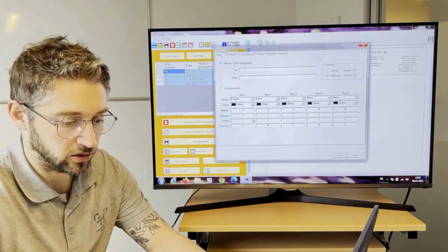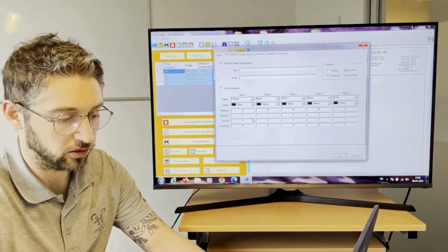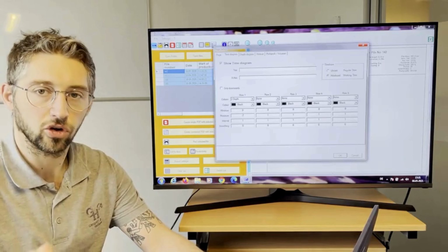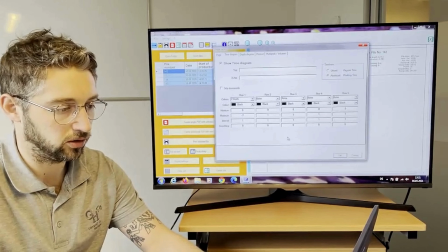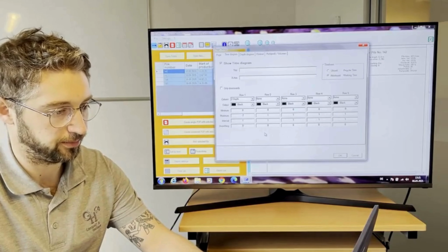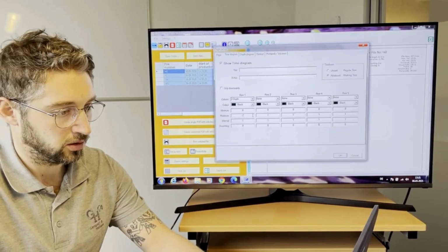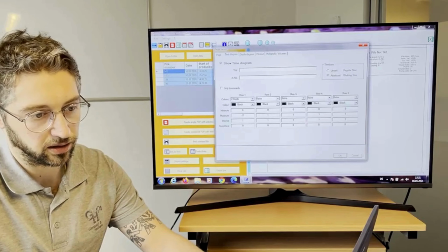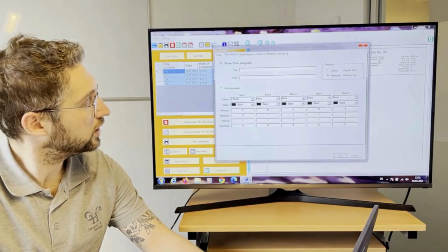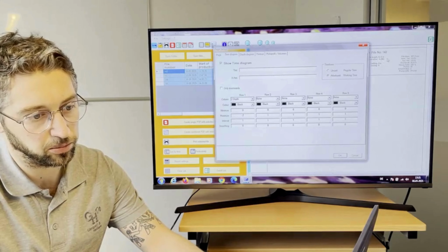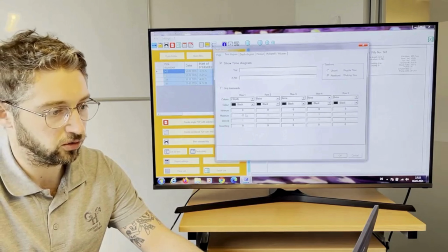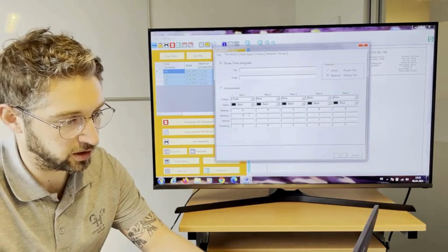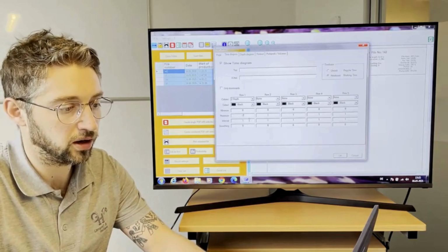because here you have to be aware to type in a negative number, because we go downwards and this is negative. So I know that this pile, you can see it here, is 6.14 meters deep. So I hit here -7 and an interval of 1 meter.